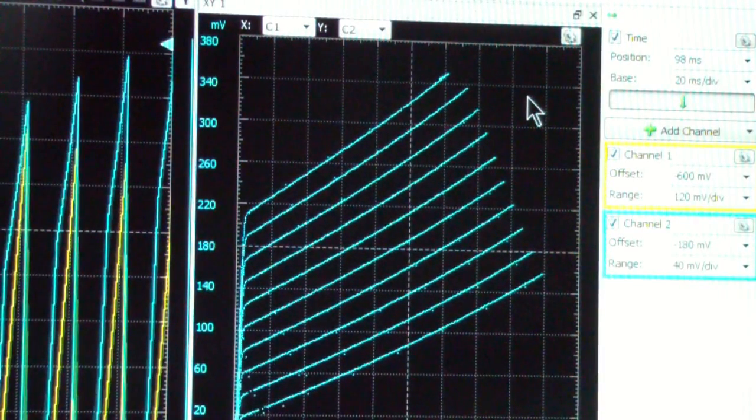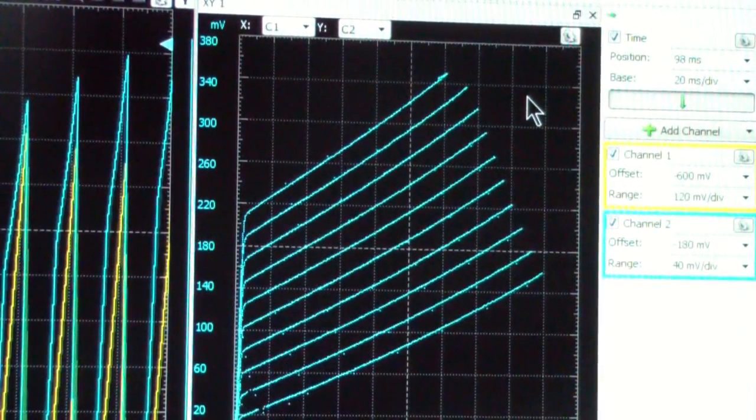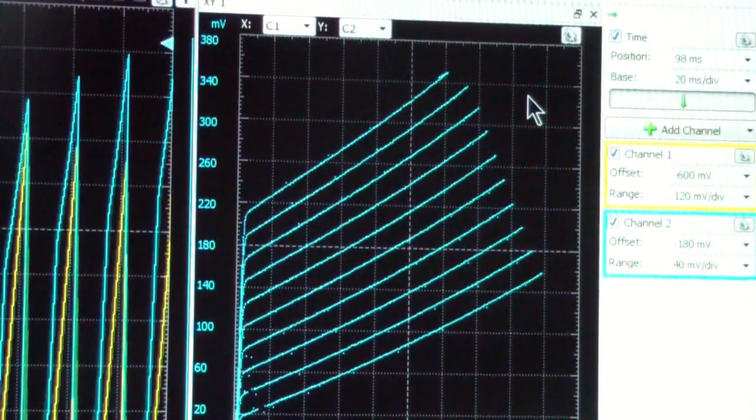We have improved the current sense by using a current mirror. And we have produced what I think is a usable curve tracer. So let me show you the final circuit that I wound up with for those of you that might want to duplicate it. And once again, this is for an NPN transistor. If you change the voltages around, you could also do the same thing with PNP transistors, and you can, as I've pointed out in a previous video, also use this to plot the characteristics of field effect transistors as well, but I won't go into that, at least not in this video.